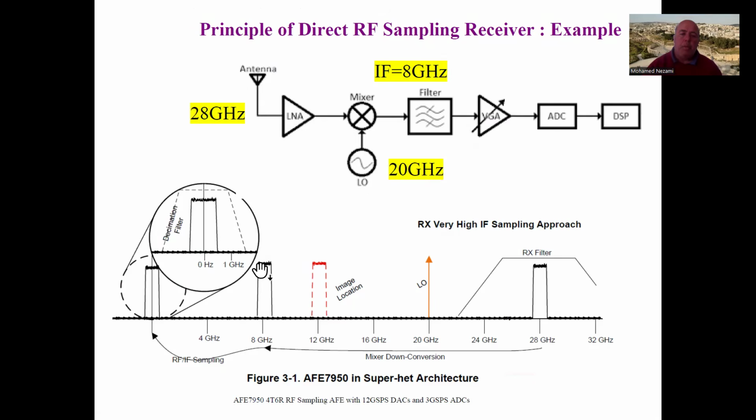And then you get to be at 8 gigahertz, which is this here. Now 8 gigahertz, you digitize it, and then that's where you actually get it to here. Now you could, if you want, do this. This is, of course, the superheterodyne receiver architecture. This is the methodology. And of course, you end up with all sorts of issues, having to reject the image, and of course, you've got a very complex synthesizer and mixer and so on, and spurs and harmonics and so on.